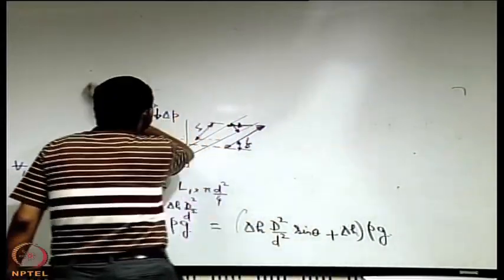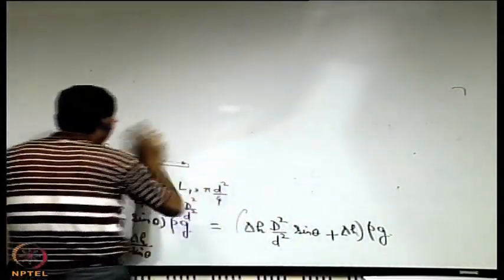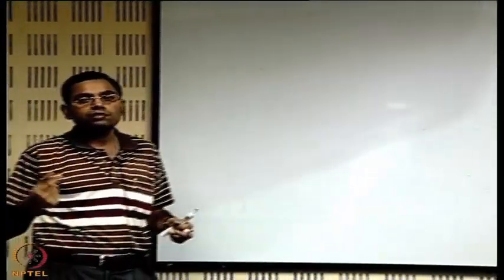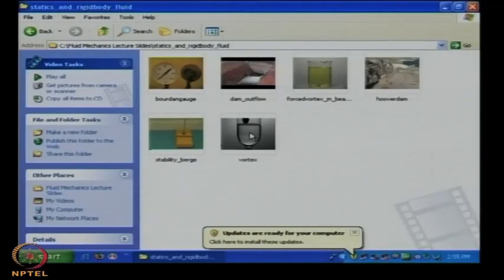Now, it is not just the manometer that is commonly used for measuring pressure differences. If the pressure differences are not very large, sometimes there are inexpensive means of measuring them, and one such example is a pressure gauge. A pressure gauge is an indicator of pressure at a point relative to some other reference pressure. Very often that reference pressure is the atmospheric pressure, and therefore it implicitly many times reads the gauge pressure. We have earlier defined that the gauge pressure is the pressure relative to atmospheric pressure at that location. So, we see an example with a demonstration of a pressure gauge.